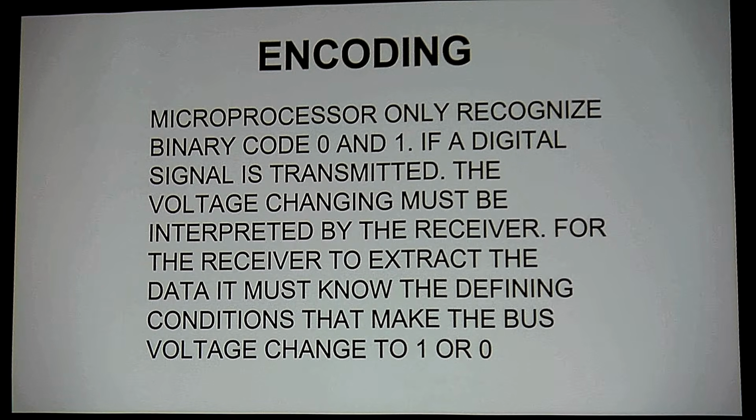Encoding is a way that we're going to send electrical pulses, high and low, ones and zeros, right? Boolean code, ones and zeros. It's the only thing that microprocessors understand. It's either high or it's low. It's either a 1 or it's a 0. Now, the 1 or a 0, I have to have a definite time in order to make sure what that is. That means I have to have bits, and I've got to know how long each bit is. This is all what's defined in the standards, right? So a lot of this is going to be set out. It's going to say, I need this bit time. We got to do this, we got to do that. But the bottom line is in order to do the encoding,